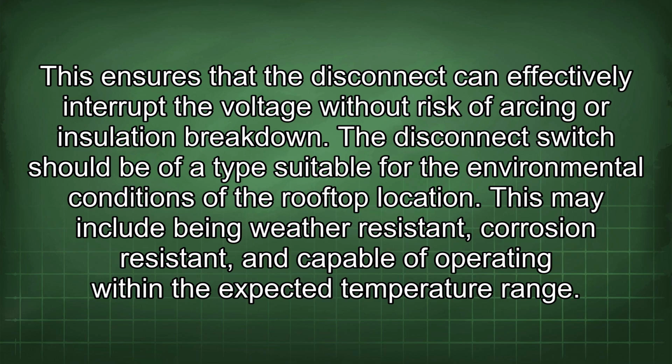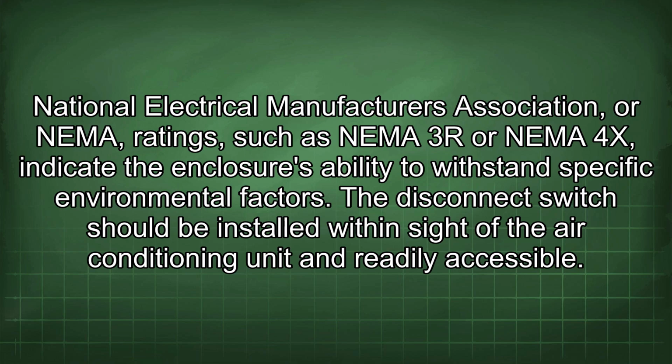The disconnect switch should be of a type suitable for the environmental conditions of the rooftop location. This may include being weather-resistant, corrosion-resistant, and capable of operating within the expected temperature range. National Electrical Manufacturers Association, or NEMA, ratings such as NEMA 3R or NEMA 4X indicate the enclosure's ability to withstand specific environmental factors.